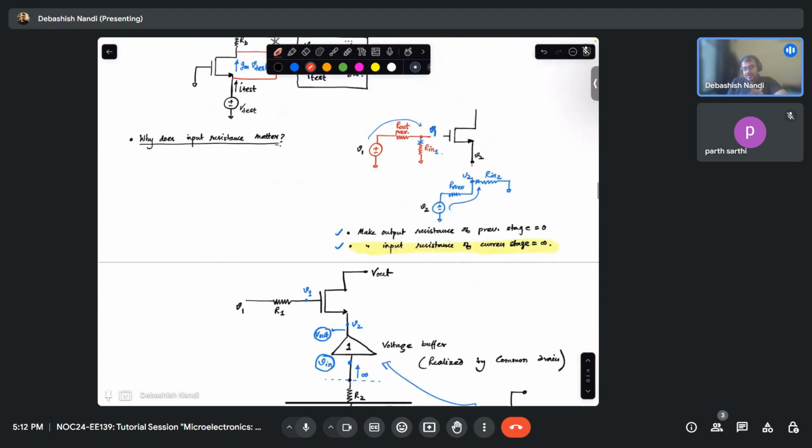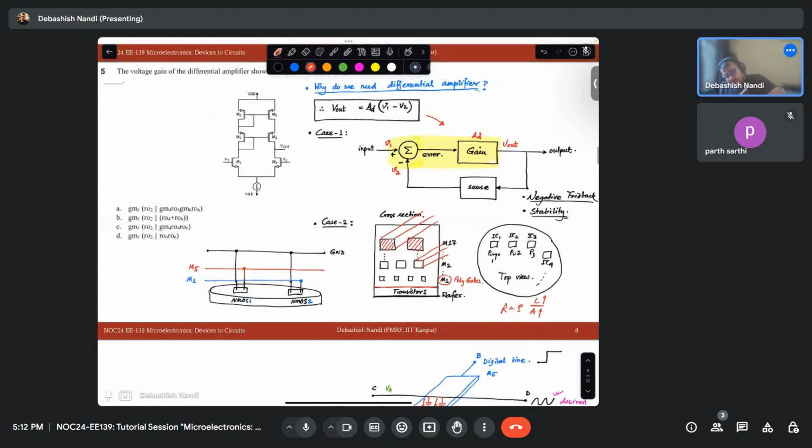in the main question, we can analyze one additional block is there. Let's say this additional thing is there. Otherwise, everything we have analyzed in this question. So how to take care of this? This is nothing but your cascode PMOS on top of your NMOS differential amplifier.